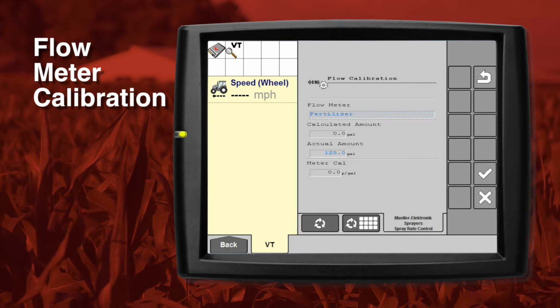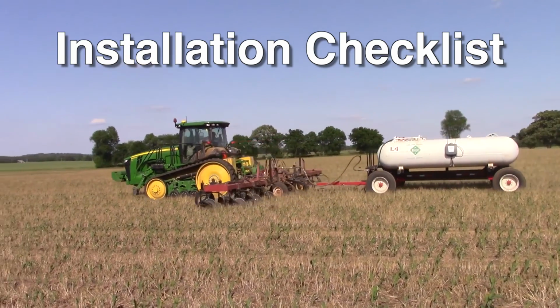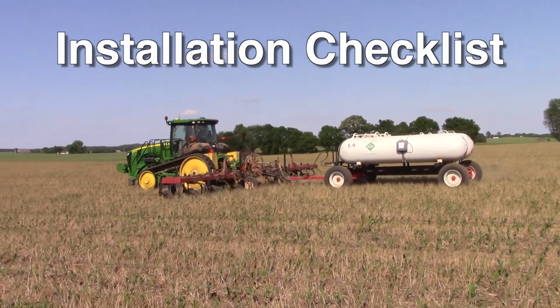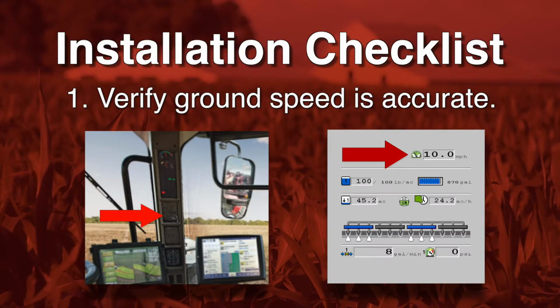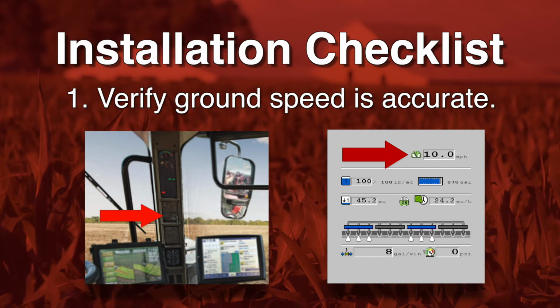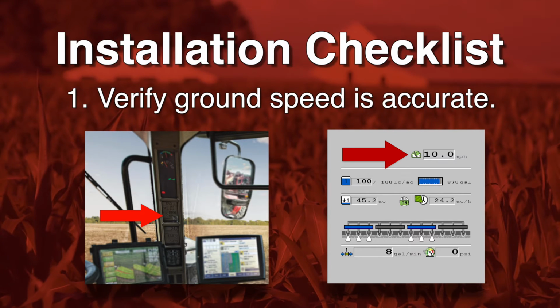The final steps of the installation process are to go through a checklist of 6 things to confirm and double check that your system is ready for operation. The first step is to drive the tractor and verify that the ground speed is functioning and accurate. While traveling at a consistent speed, confirm that the tractor display or the tractor A-post speed matches the speed displayed in the universal terminal.